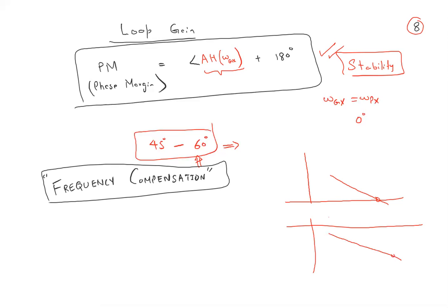Okay. So this is the omega px and this is omega gx. So our point was that at this moment, if we are given a task, okay, your phase crossover frequency is here, gain crossover frequency is here, and your phase margin is 30 degrees. I'm just putting some numbers. And somebody tells you need to improve your phase margin because it's less.